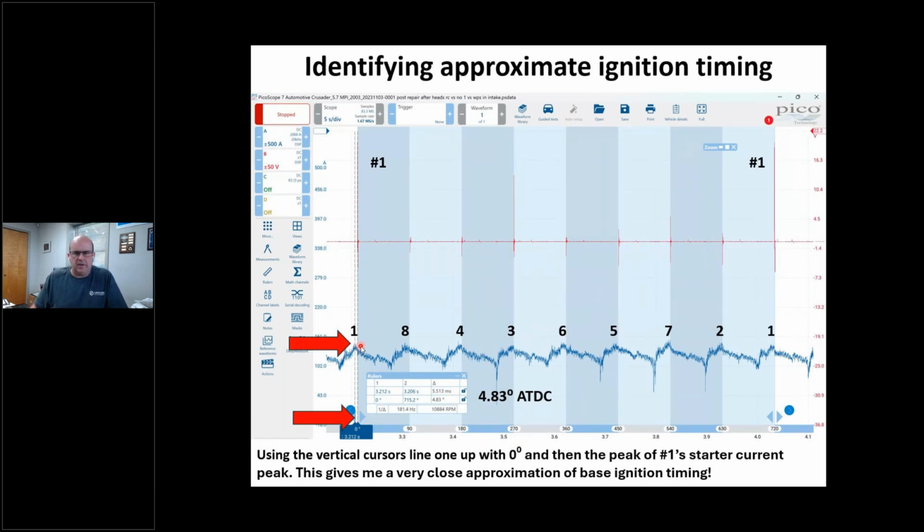I've got a case study that I'm not going to do today, but I had a customer send me a jet ski engine this year, and the key shifted in the flywheel, and the spark is happening over here, almost in the valley, almost 45. I think it was 60 some degrees late. Okay, engine wouldn't start, and it was a rebuilt engine.